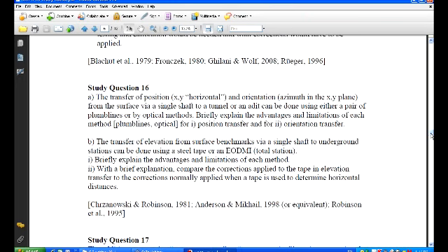So you can sight to the target from the surface, turn it so that the target portion of the sphere is looking downwards and you're maintaining the same point, and then the optical plummet looking up could then be centered with the translation stage underneath the center of the sphere, which then transfers the horizontal position. And if you have two of them, then you've got the base to transfer the orientation.